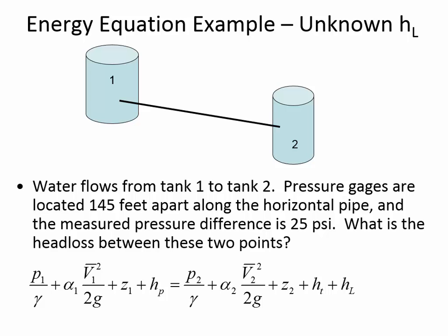we're going to start graphing energy in the system. And a head loss like this, being a length, is actually relevant because if we were going to graph the energy between 2 points, you'd measure how much higher the piezometric water surface rises at 1 versus 2. And this 57.7 means the water level would rise in the pipe 57.7 feet less at location 2 than it did at location 1 because of that energy loss.